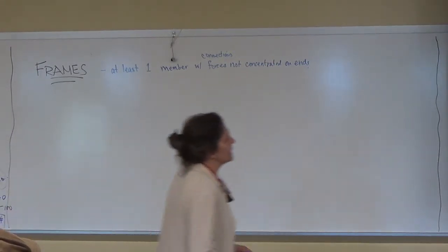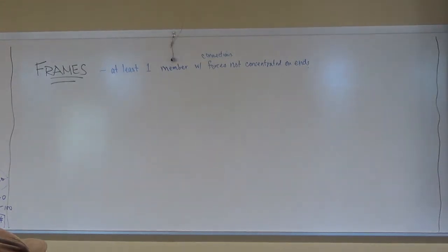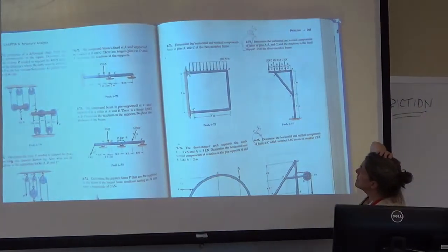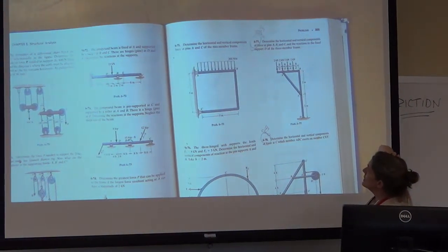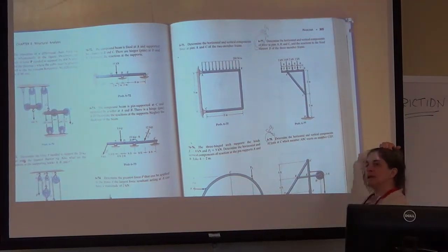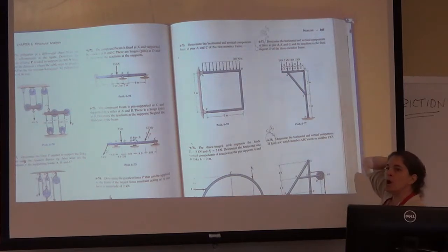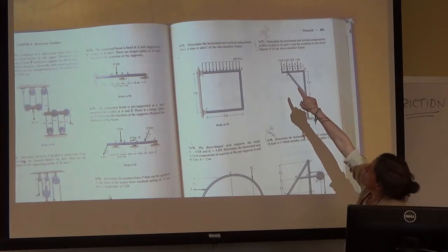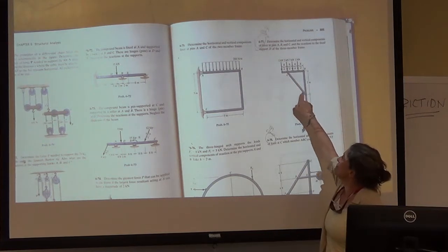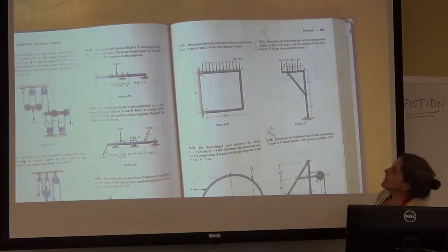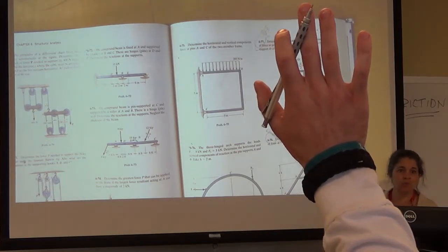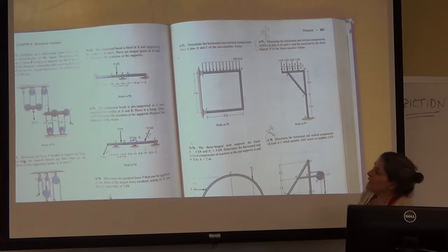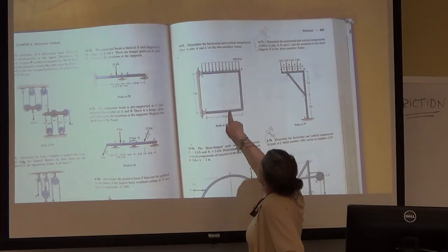Okay, so when we look at some of these problems right here, of these two problems, are there any 2-force members here? Yes. Which one? The one on the top right. Okay, give me a label. You know how to label members. Problem number what, and what is the name of the member? Problem number 6-77, BC. Okay, problem number 6-77 and AC is a 2-force member. Is there another 2-force member? There is. It looks weird, but it is. Matt? Problem 6-75, member CB. Yes. Notice the member curves, right?